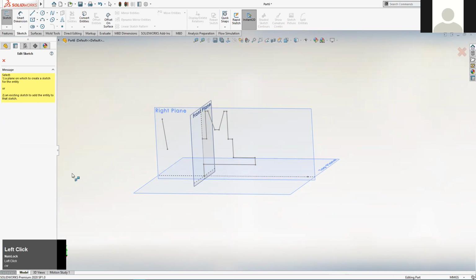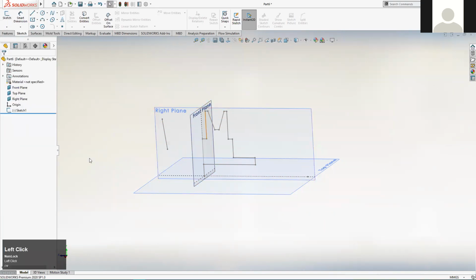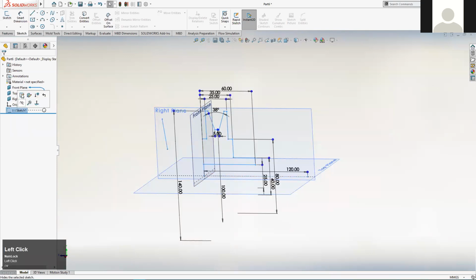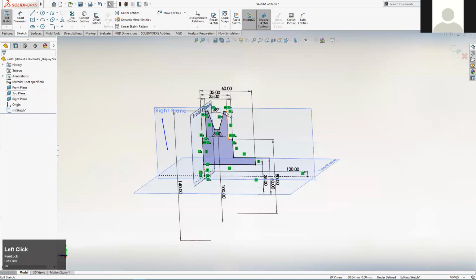So again, basic concepts of SolidWorks. People often get into this situation and then they go, well, why am I not back in that sketch? It's because you're not editing it. When you're editing it, the lines will either be colored in blue initially or in black if they've been fully defined. So when they're gray, you're not editing it. If I want to edit it, click on it there, go to edit sketch. Now I'm back into Sketcher. Now I'm editing this sketch.